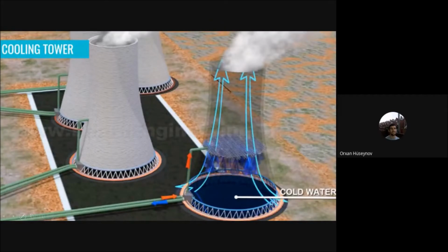At this cooling tower, what we have is that the hot water out of the Rankine cycle comes into contact with the air, here you have the air, and this air is cold, and the water here is hot. Okay. It gives its energy to the air, but some of the water leaves the system.